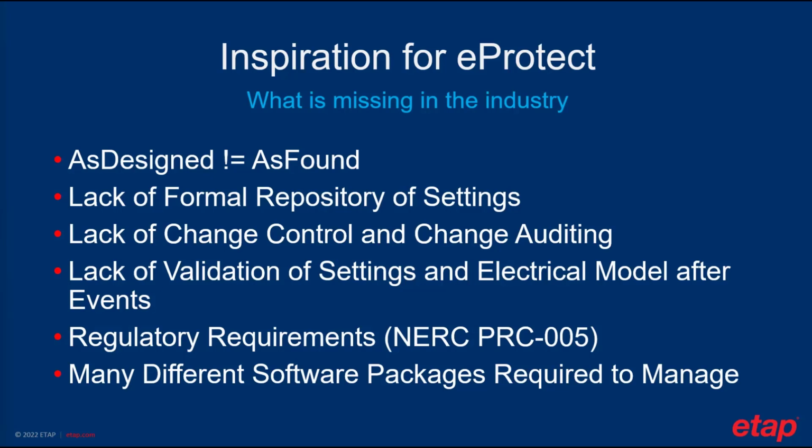A lack of formal repository of settings. Oftentimes the settings are just whatever happened to be on the relays, and there's no actual formal repository that ensures that you know what the settings are at any given time. Lack of change control and change auditing. As new people join the company or just through time, there's no way of ensuring that you know which users made changes.